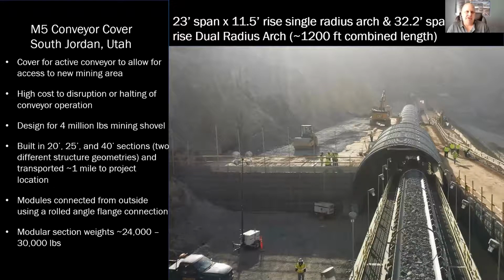And this consisted of two different structural geometries. One was roughly a 23 by 11.5 foot single radius arch, and then a 32 by about almost 19-foot rise, a larger dual radius arch, kind of a horseshoe shape. And the reason for the two sizes was that the conveyor had a slope to it at the end, so we needed a taller structure to allow the clearance around the conveyor.